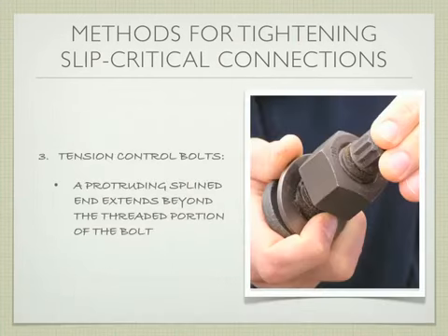The last type, which I have here, you guys can take this one already, start passing that around, is called a tension control bolt, and this is probably the most common method today. It's a special type of bolt. Let me take the nut off this bolt for a second. If you're looking at the bolt itself, there are the standard threads of the bolt, and then at the end there's this geared spline. If you look carefully at the one that passes around, there's a slight indentation in between the geared spline and the threads.